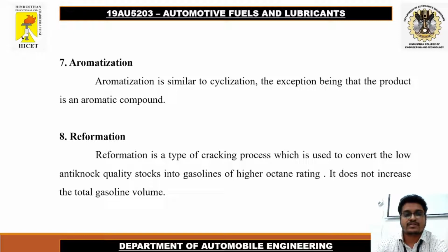And last process, reformation. It is a type of cracking process which is used to convert low antiknock quality stocks into gasoline of higher octane rating. It does not increase the total gasoline volume. That is, here the gasoline volume is not being altered, rather its anti-knocking quality is being increased to get the higher octane rating for better performance.